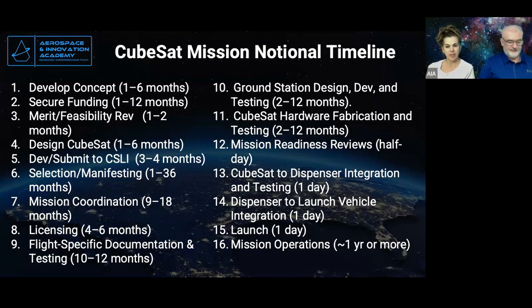With the vibration test, I think you alluded to it either with the payload Minisode or the one from last week, but you want to make sure that it's simulating what it's going to be like during takeoff so that parts don't become disassembled. Is that right? Yes. Every launch vehicle has some fundamental frequencies based on the type of engine and the kind of vibrations that are going on in the combustion chamber and as a function of the aerodynamics and the thrust.